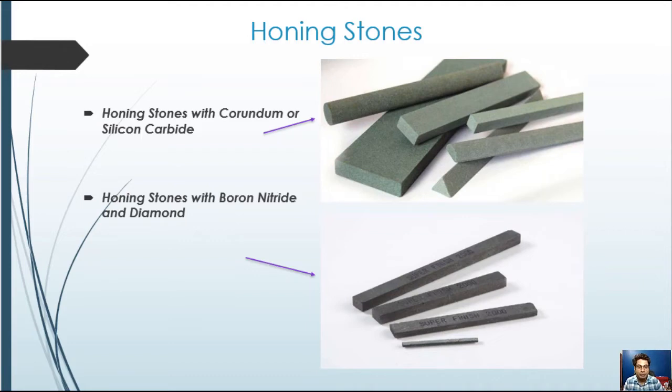By keeping the process at the right temperature, both the cylinder liner and the stone can be preserved to ensure quality and lower production cost. The most common fluid used is mineral oil. This is due to the high viscosity and high flash point. Another benefit of the oil is that it does not irritate the skin of the machine operators.